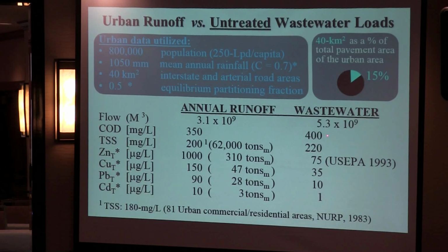Chemical oxygen demand, quite similar. Total suspended solids, those solids that remain suspended in an Imhoff cone for 60 minutes, actually quite similar. Now, that excludes settleable solids and sediment, which would actually make the total solids number closer to 600.